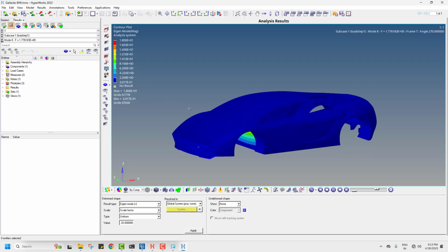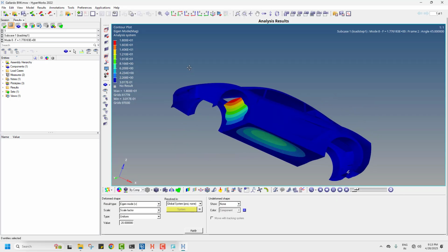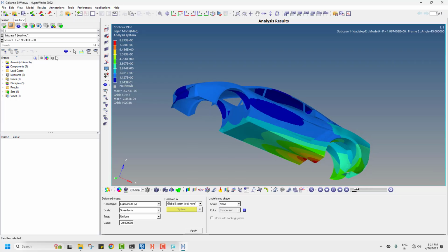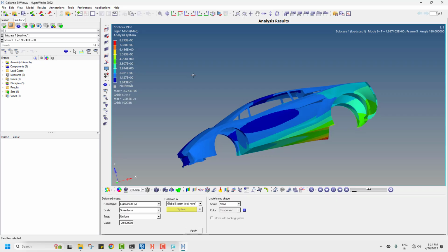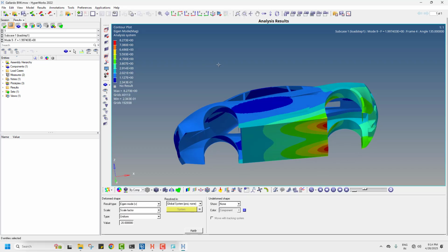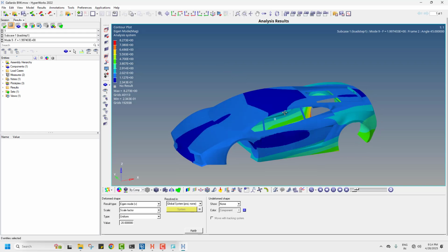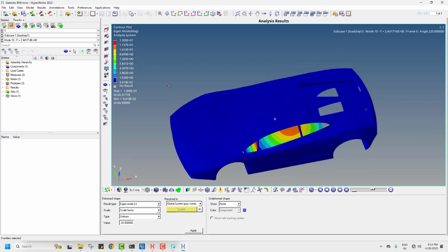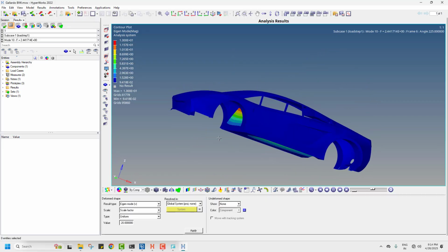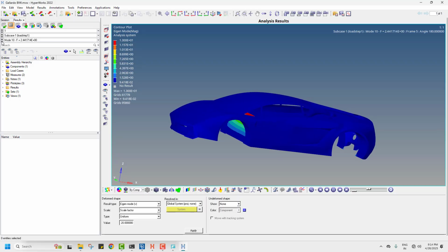The eighth one is the bending mode, right? It's a global bending that is happening. And then the ninth one again a torsion. It is again the back mode, means towards the rear end, right? It's pumping. Correct? And now the 10th one also you could see, it's again a bending mode, right? Similarly, you're gonna have the other modes.